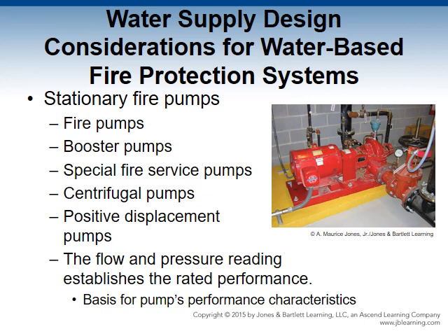Churn measurements, also called shut-off, minimum, deadheading, or no flow, are taken when the pump is running at rated speeds with no water flow. Peak performance, also called maximum or overload point, is actually 150% of the rated flow at 65% of the rated pressure.